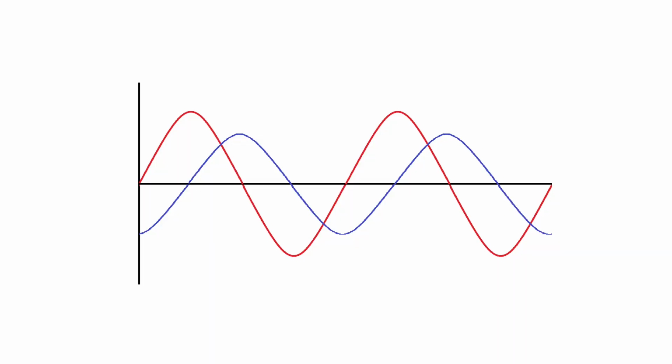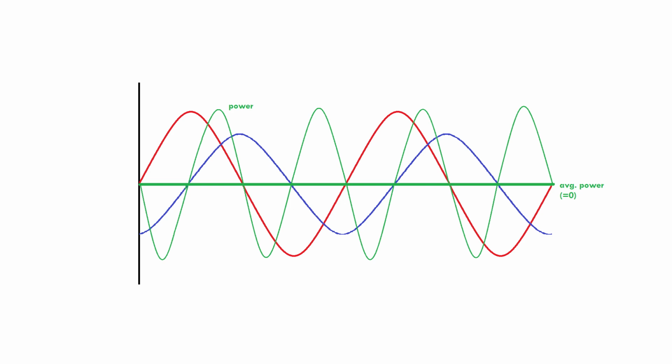So apparently, when this machine is at this specific point in time, it's supplying power back to the power outlet, okay? So now it's consuming negative power, which is another way of saying it's supplying power back to us. And again, if we calculate the power usage for every single point in our graph, we get the power sine wave. But the power sine wave now is different, right? Because now it's got negative values.